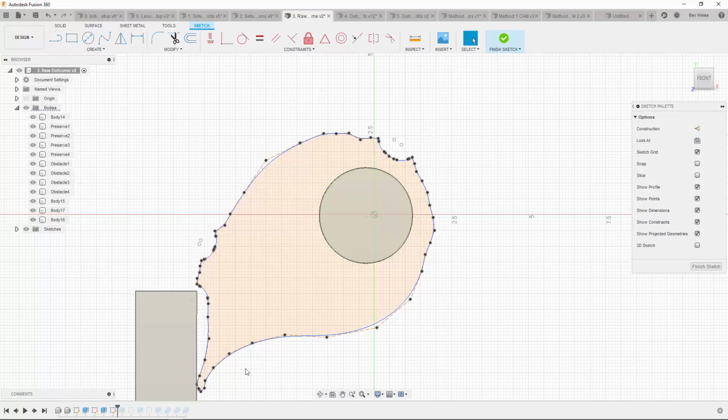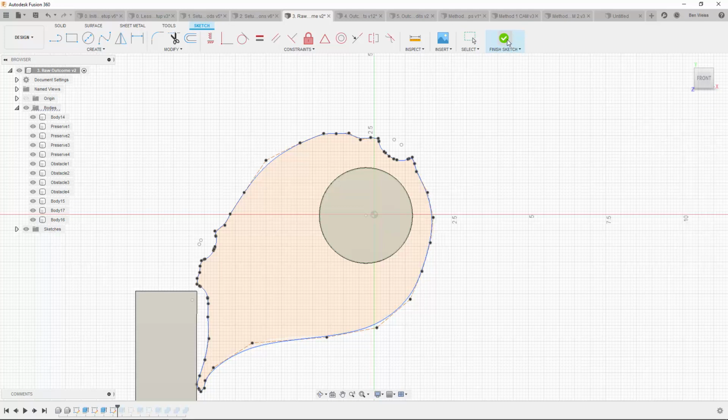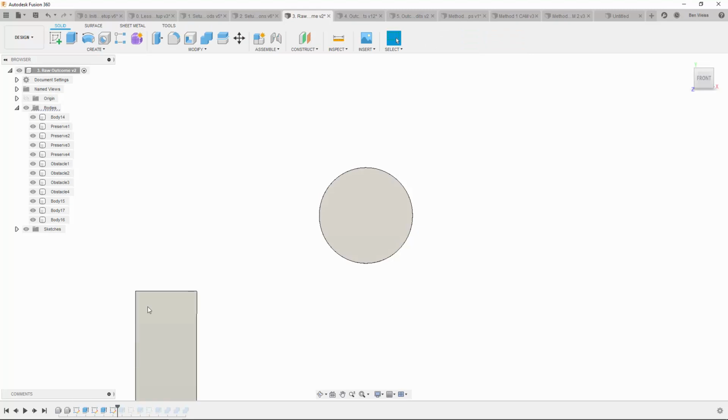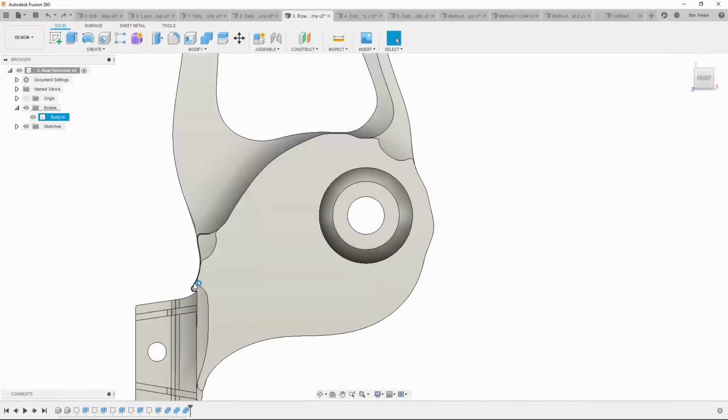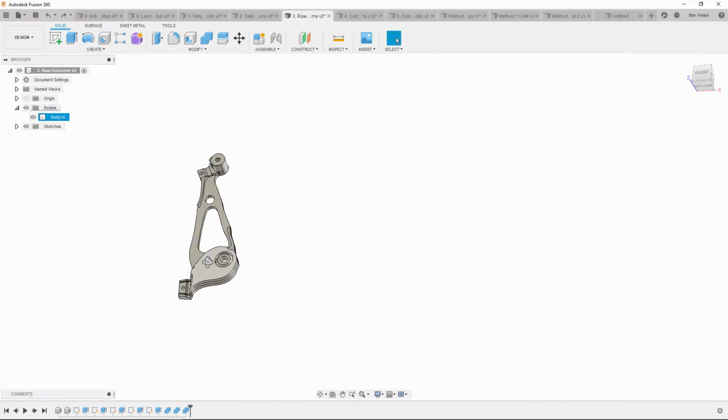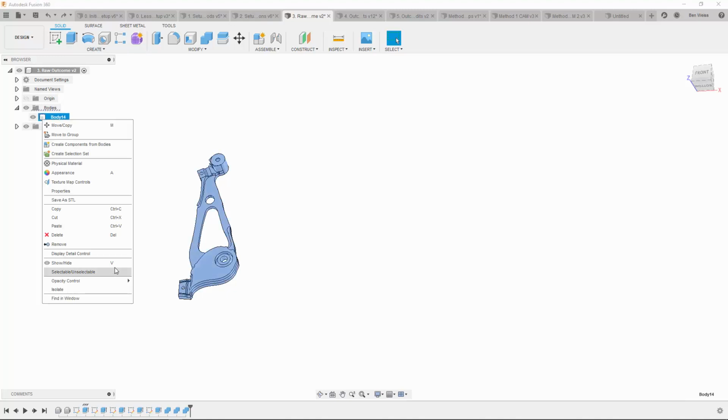First, we'll work on cleaning up this spline. Typically, I find that the generative outcomes have a little bit too dense a spline structure for my liking, so I'll come through and delete a lot of these redundant points. Ooh, I skipped a step. Never mind. Stepping back. Before we make any of these changes, I want to make a backup of the original shape so that I have some sense of how far I've drifted from the design created by the optimizer. So to do that, I'm going to take the body and copy it.